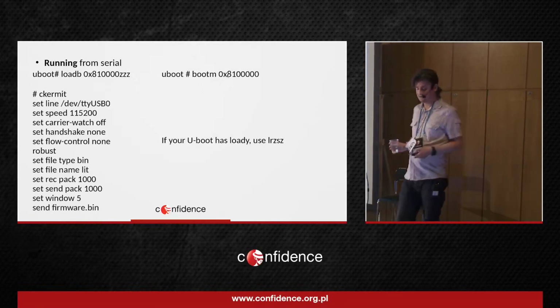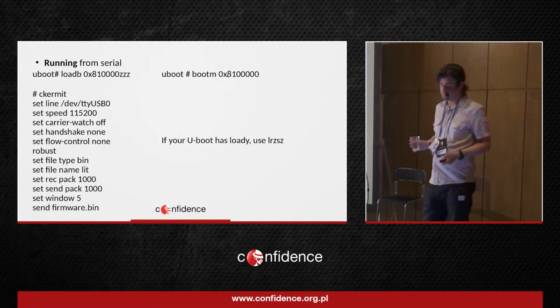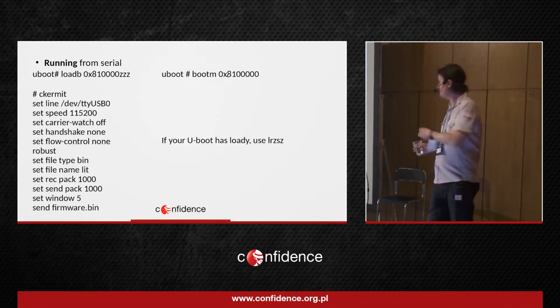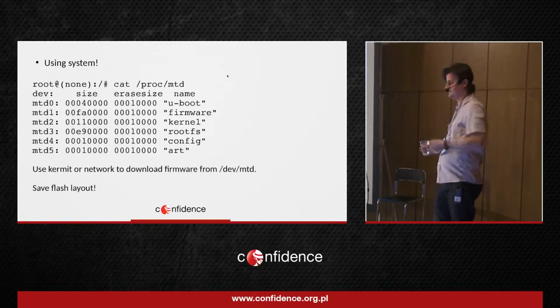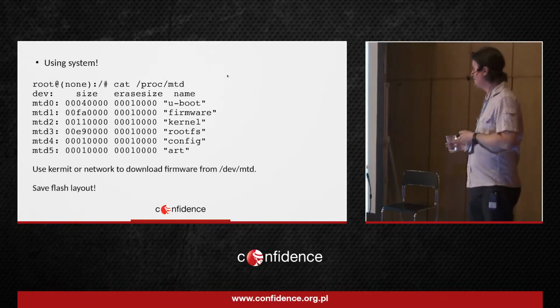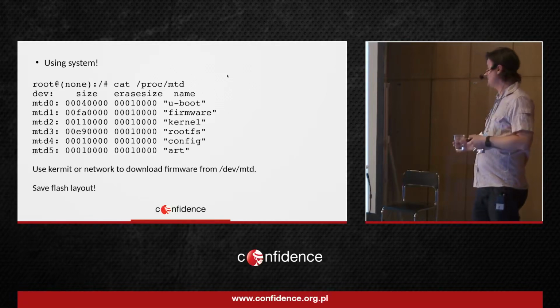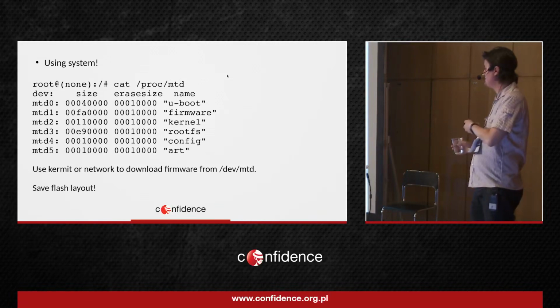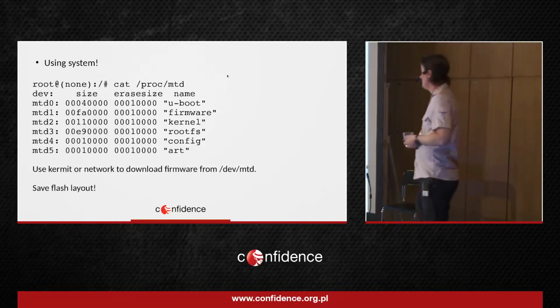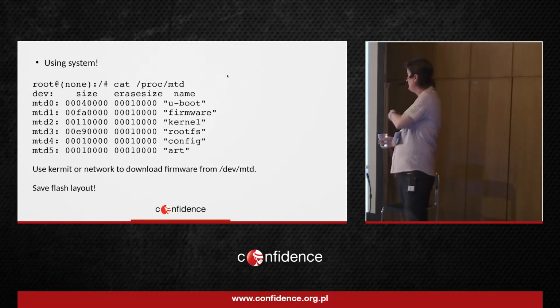If your U-boot doesn't have the loadb command, which is possible, you should use loady. It's the Y modem protocol, and there is just a different command for sending files. But it's possible too. So, when you have a system, you of course have a root prompt, and you can look around at, for example, what's in the original rootfs of the device. In proc, there is a partition table from the MTD device.